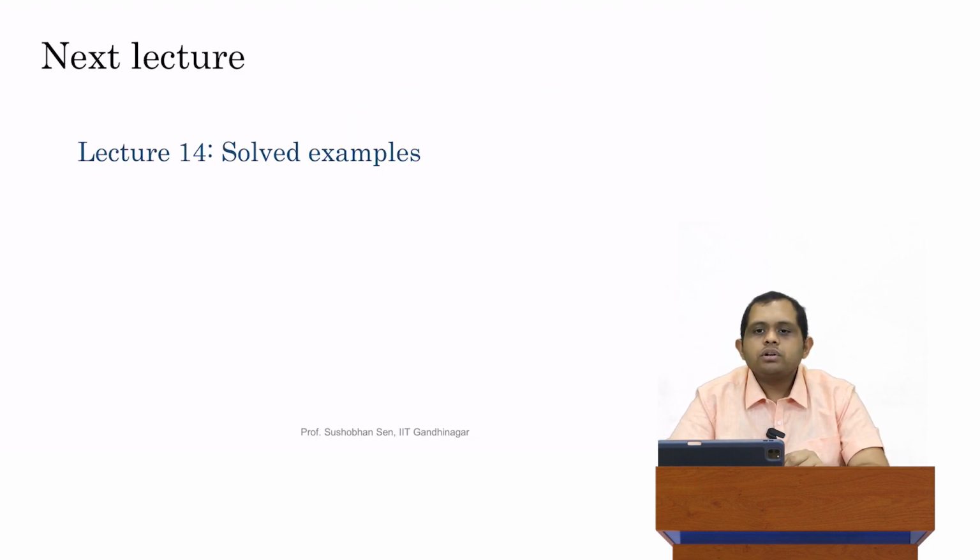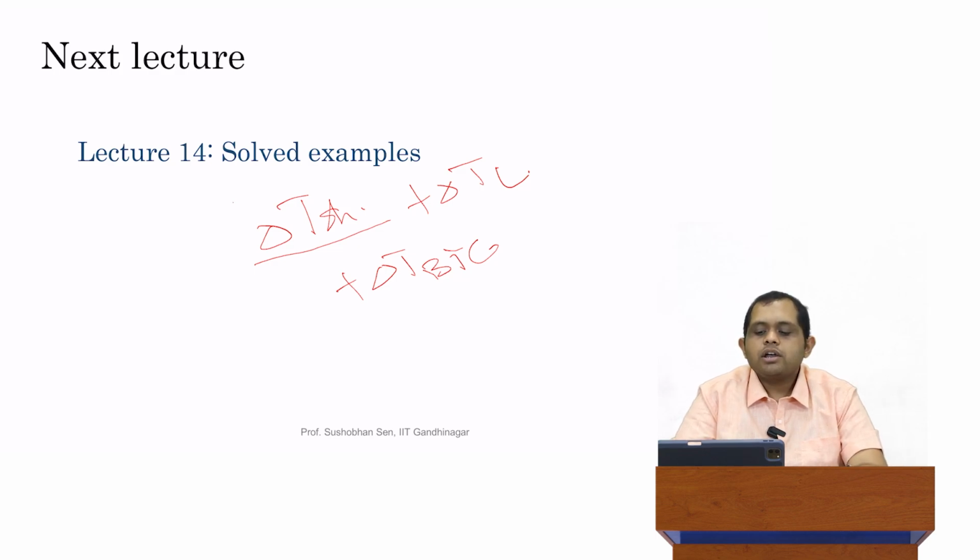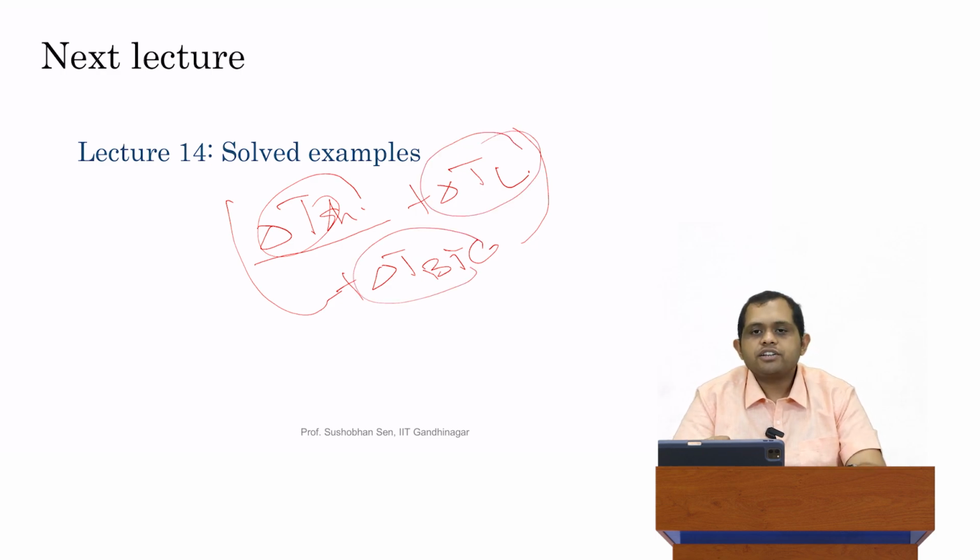Okay, so to conclude, in today's lecture, I showed you built-in curling as well as moisture. We looked at the Bazant and Baweja model to calculate this delta T SH. We calculate this value and then we add it to our delta TL, and we use that for the curling stress. To that, we also calculate delta T BIC to take built-in curling, or zero stress temperature difference, into account. We saw how to do all these calculations. These two calculations we saw today. Delta TL calculations we saw in the previous lecture. And the first lecture in this series was related to this phenomenon of climate in general.